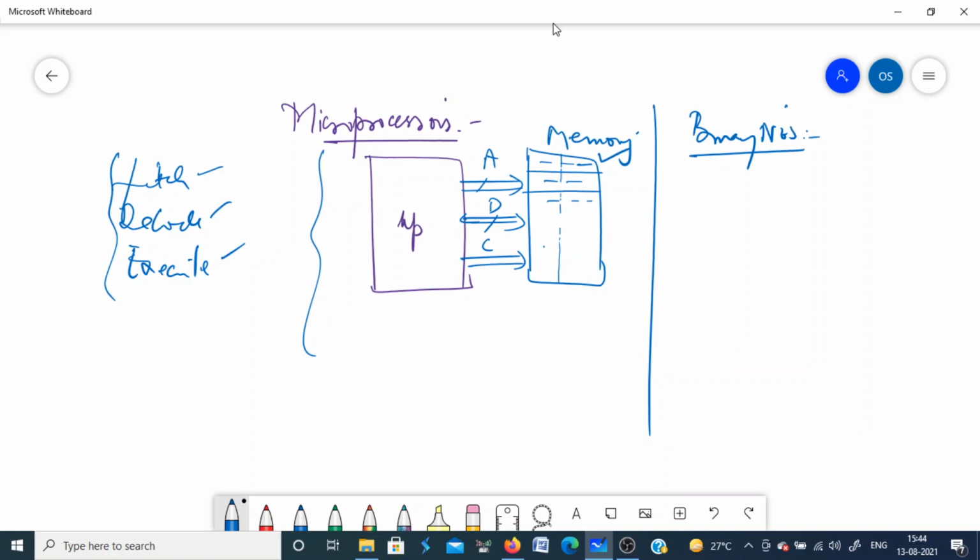Okay, so like we have said, if you have an 8-bit processor, you can have 2 to the power 8, or 256, different bit patterns. Okay, so each bit pattern is used for a particular task or operation, which is called the operation code. So you have an 8-bit opcode for each instruction. Maybe suppose 10010001. This is used for a particular application, suppose to add two numbers or to increment the data in the accumulator or whatever it is. So this is decided by the designers.